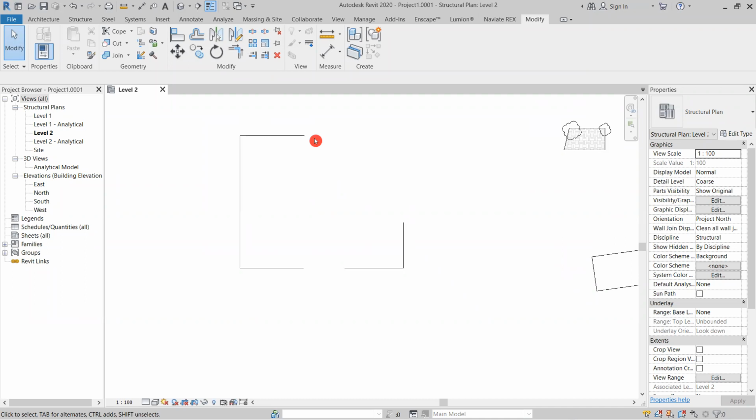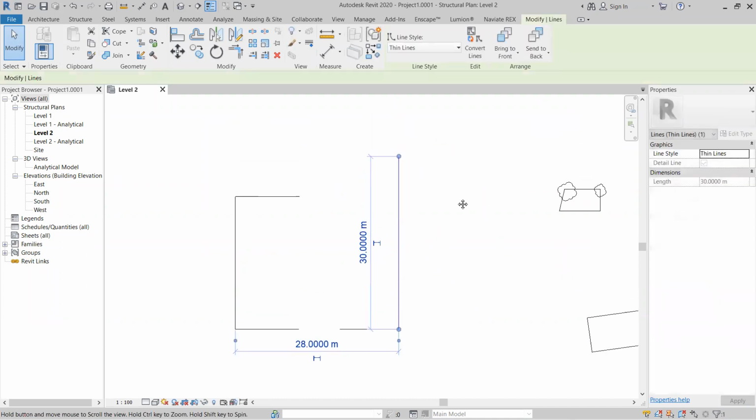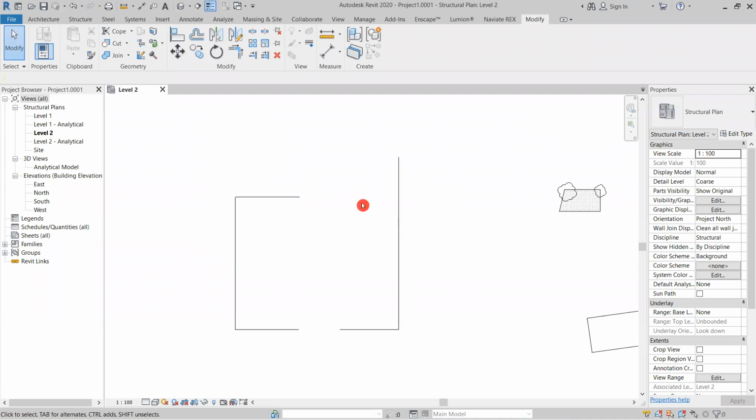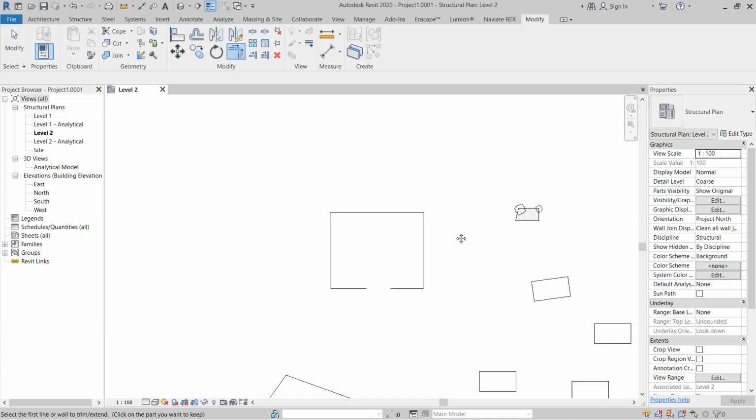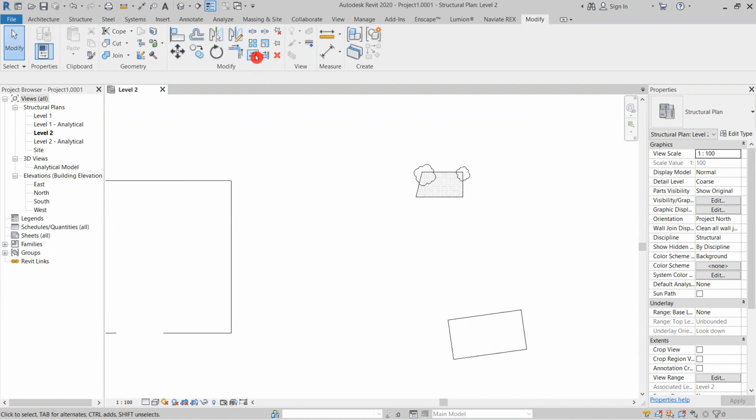Yeah, you will get a recording, right? So trim is nothing but, the line is here. You want to trim this line from the particular objects. If you want to trim the objects, you can align these particular lines. So click here and you can do like this. Okay. So it's just a 2D line, right? Then here is the option called trim extend a single element.